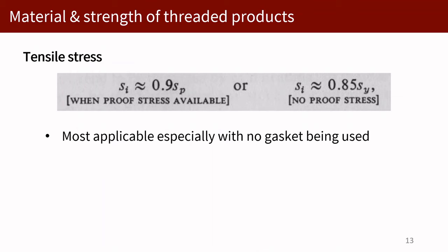Kay kung maggamit og gasket, it will incur less compressive deformation sa mga connected material, since naa may usa ka additional nga member, the gasket, which is often softer sa imong connected parts. Okay, so mao ni ang gamiton for gasketless nga mga connection.